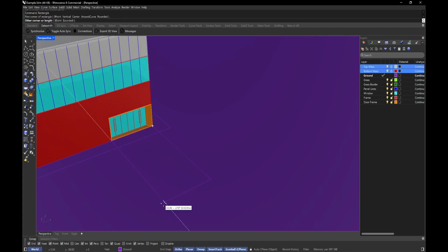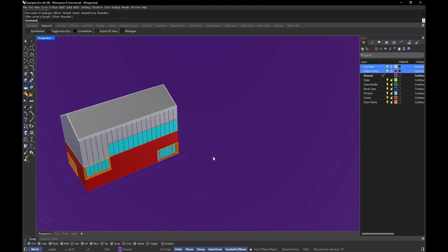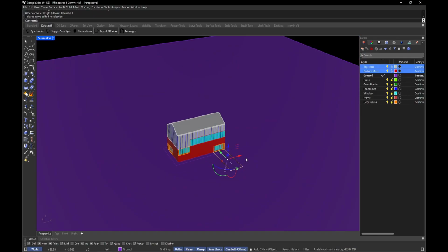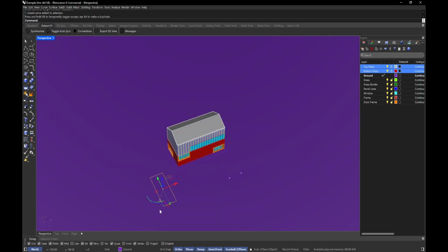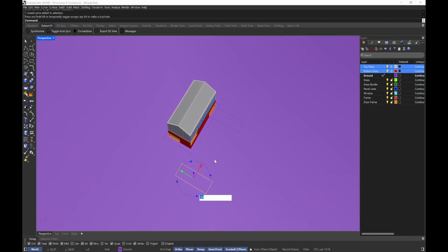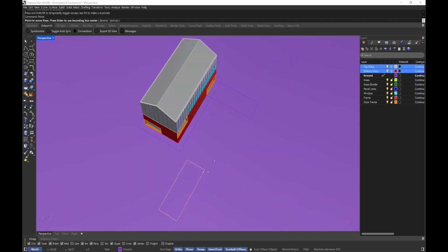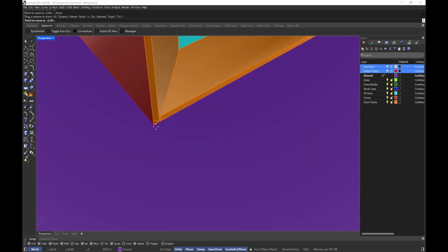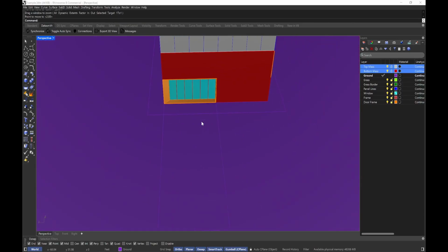And I'm just going to make sure I'm tracking correctly. I don't know. I might just go something like this, maybe. And I know that this duplicates. Let me go like this. Let me rotate it 90 and move it like this here. I'm just zooming within. That's the nice thing about Rhino. You can zoom within the command.